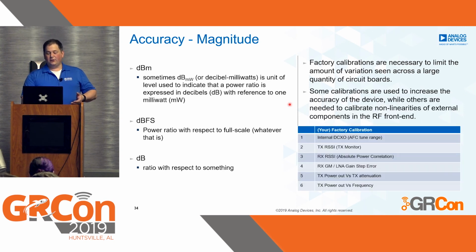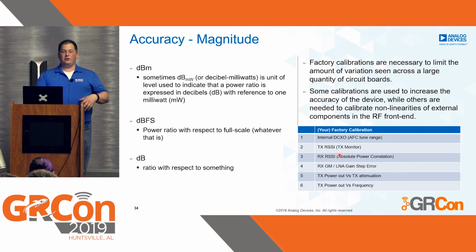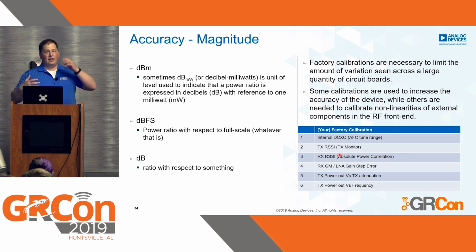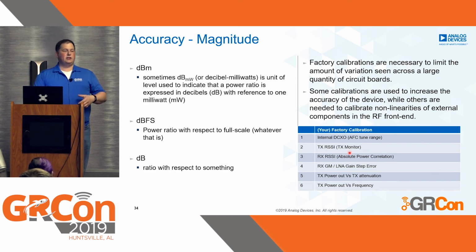And so there's calibrations that you can do on all your radios, but you need to calibrate it to something else. So even us in our lab, we will have Plutos that have been calibrated and are actually, from a power input perspective, as good as some of the instruments we have, but we use those instruments to calibrate the Plutos. And if we were to do that on every single one, then the prices would be so high nobody would want to buy it. So all of these things can be done. It just takes time, and you have to calibrate them to something else.